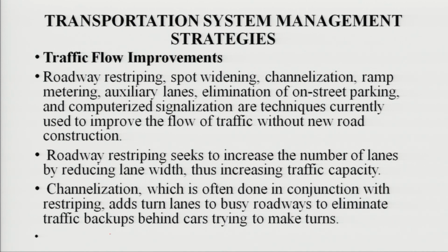Now, transportation system management strategy. First is traffic flow improvement. Roadway re-striping, spot widening, channelization, ramp metering, auxiliary lanes, elimination of on-street parking and computerized signalization are techniques currently used to improve the flow of traffic without new road construction.